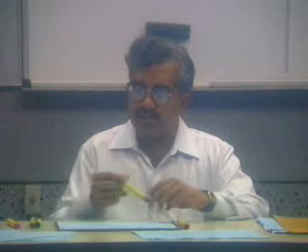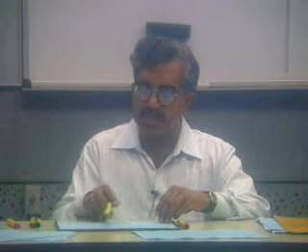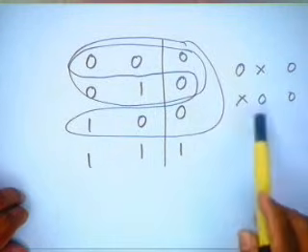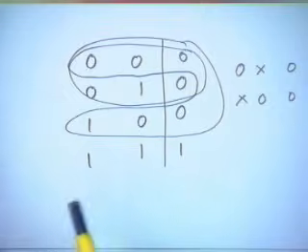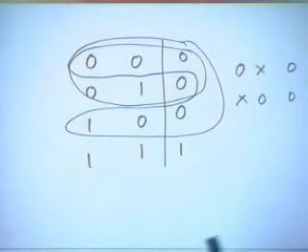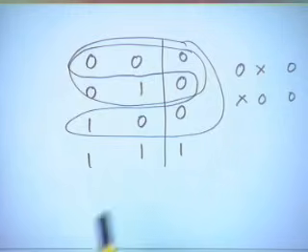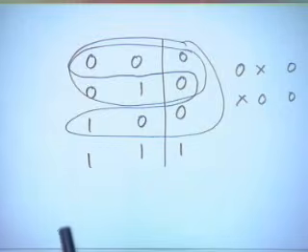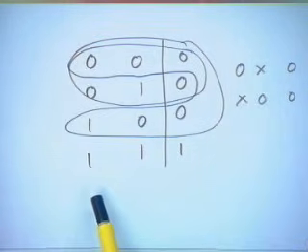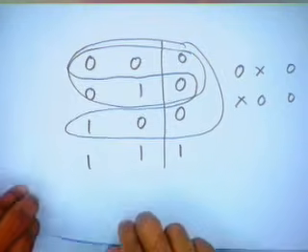And we have already seen how you can generate this, because you look at the rows where the output is the same, and if you can eliminate one or more variables, eliminate them and put them to be don't care. So you can do it using the Karnaugh map method. If it's a very complex thing, from the Karnaugh map you can look at all the inputs, which are the min terms, and those which combine can be used to eliminate some of the variables. So you can generate your singular cover in this manner.